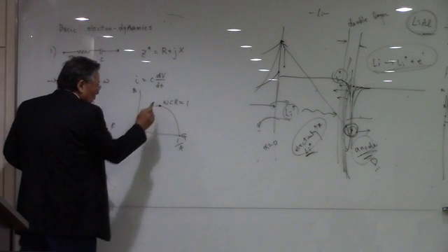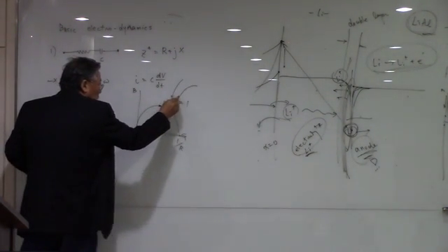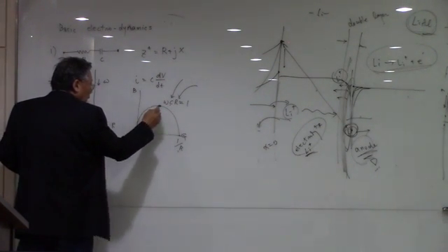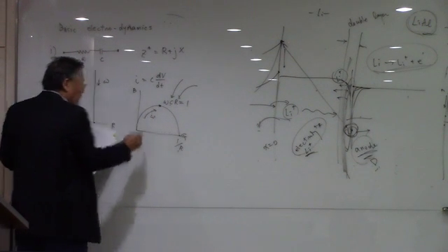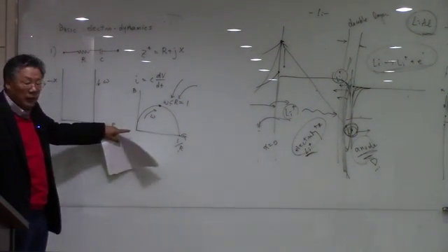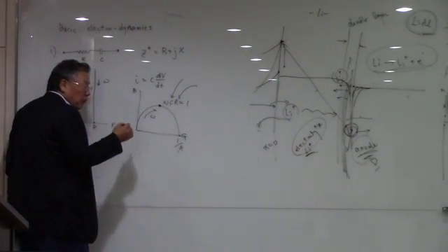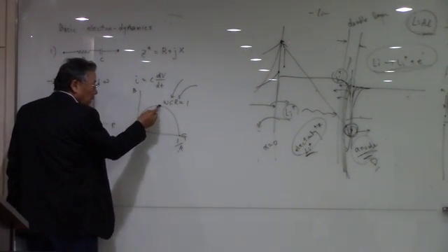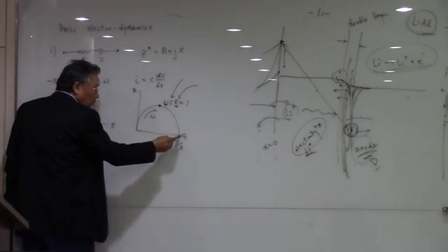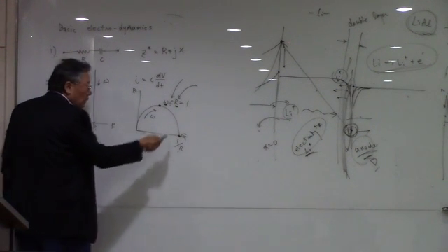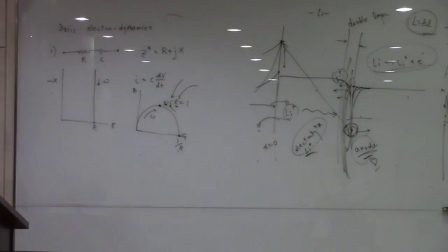So we can get information about C and R here. We're changing the frequencies experimentally from here to here, so we know the maximum frequency, okay? And then we know the R value of this semicircle. Then we can determine the capacitance here, okay?